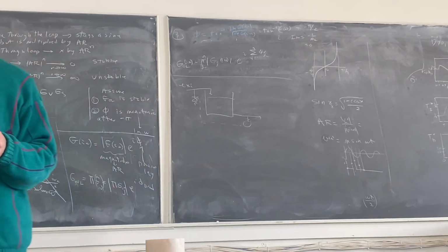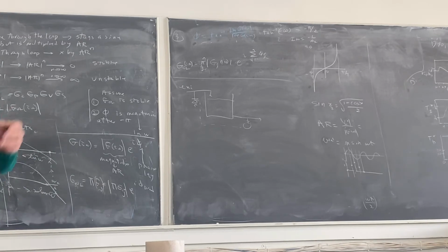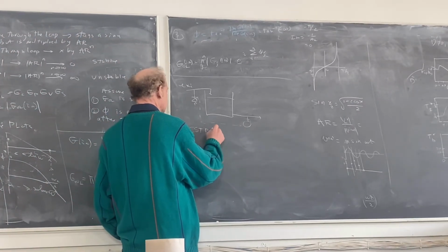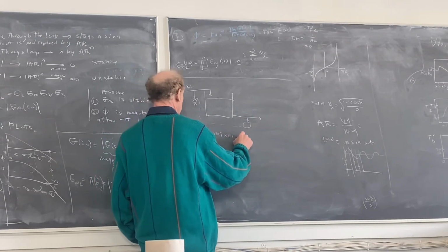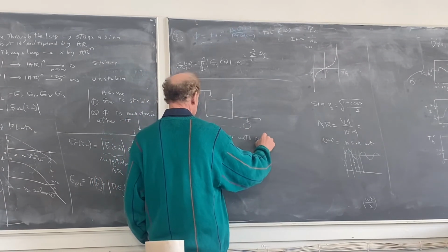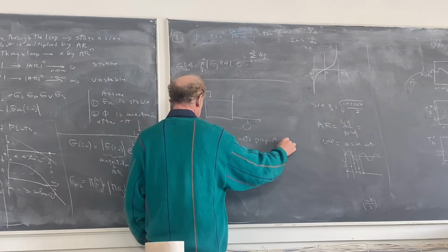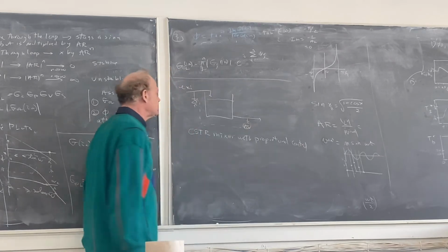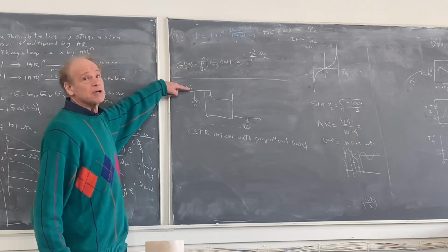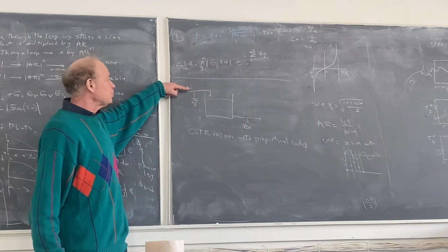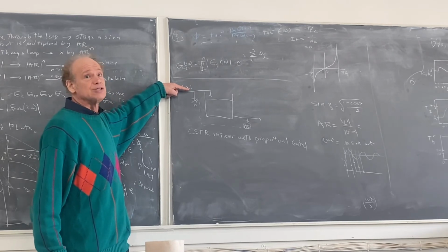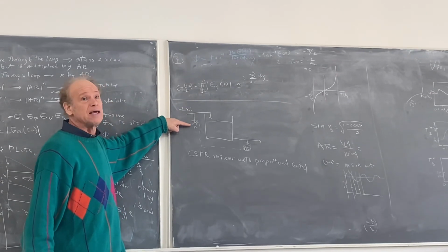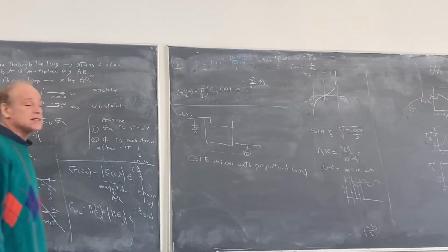So this is a CSTR mixer with proportional control. I analyze what comes out, and I have a stream coming in from a different part of the plant. If it doesn't have the right concentration of my reactant, A, because I would like a lot of A, then I can spike it with more A. So that's basically how it goes.